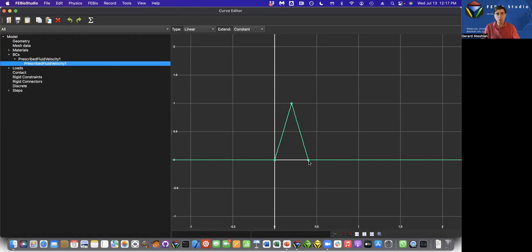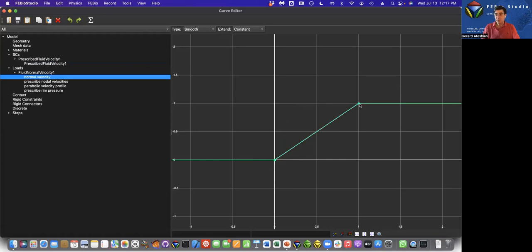It'll turn out to be sufficient to cause the vortex shedding to occur a little bit earlier than, let's say, 250 seconds. But by the same token, I'm going to also make sure that my fluid normal velocity rises more or less instantaneously. I'm going to take my time increment to be 0.1 seconds. So I'm going to let the fluid velocity be equal to 1 centimeter per second at the very first time step. Of course, if for some reason numerically it doesn't converge, then I will let the inlet velocity scale linearly from time 0 to time 0.1 in case the code needs to take shorter time increments.